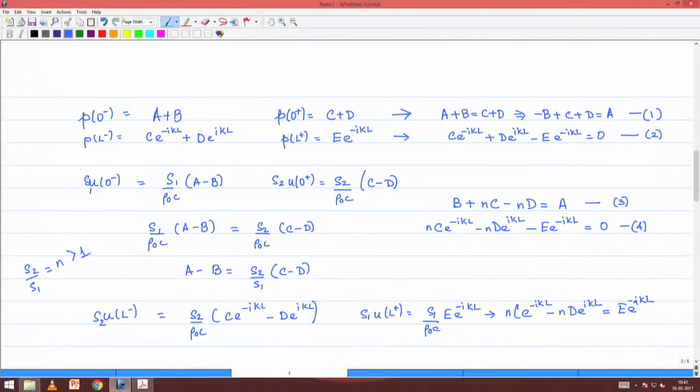Okay. So, this is what we will now redo. Therefore, for this class of problems we will try to redefine the impedance in a slightly different manner, as we understand that it is not the velocity which is important in this class of problems, it is rather the mass velocity or the volume velocity which is important, right. So, as we go along, we will redefine the impedance not in terms of particle velocity, but in terms of mass velocity.